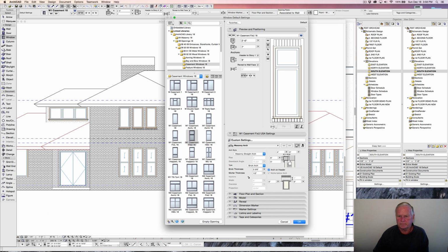It's just a look. And then as we look here, this is kind of elevation section things. I want it to protrude out 1 inch. We'll leave it as 8 inches tall, even though it's really probably 7 5/8. But visually we can leave that at 8 for the moment. Depth of it being 4. Again, that would be 3 5/8. You want to be particular, but this sort of stuff doesn't show up anywhere. And then I would really like to have the brick probably run straight up and down from the edges of the trim. So we're going to leave those both at 0.